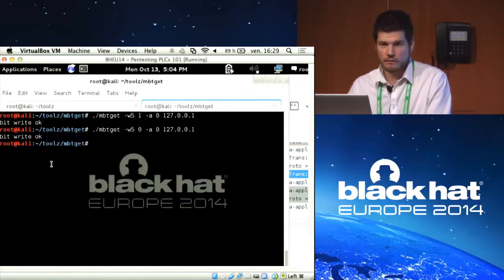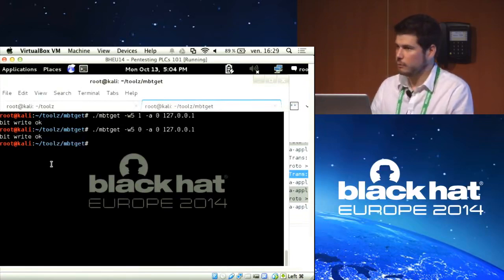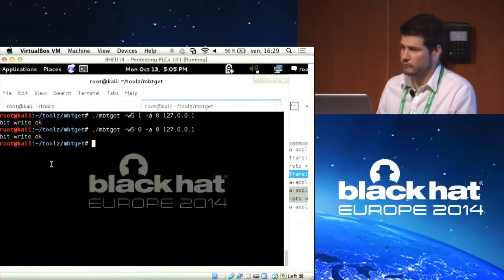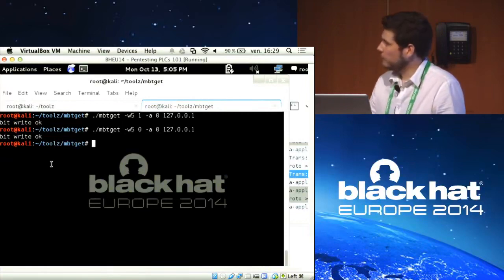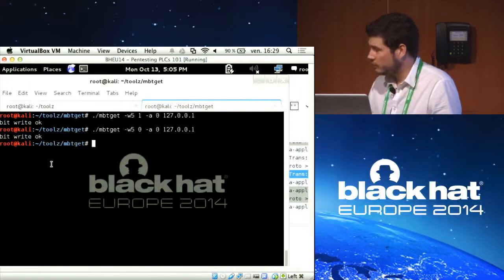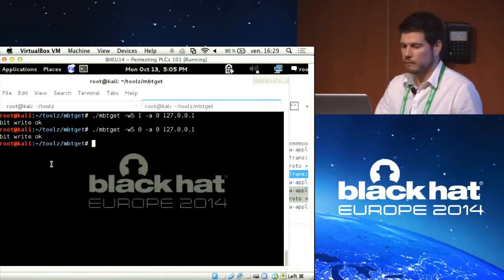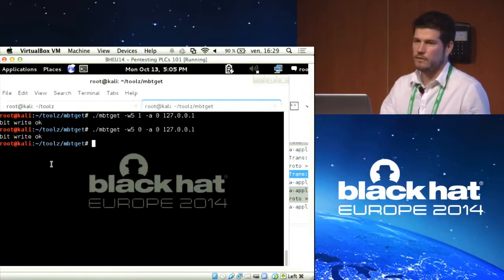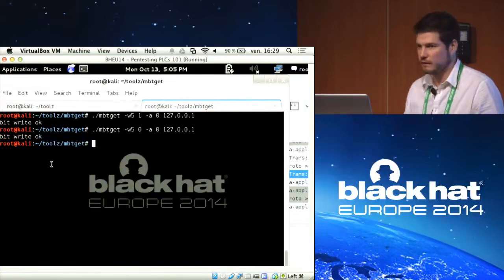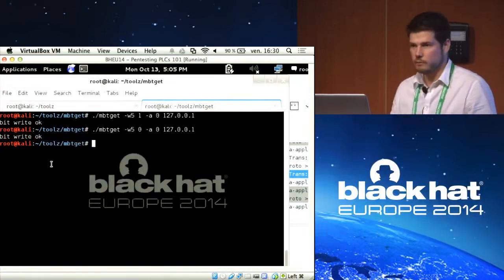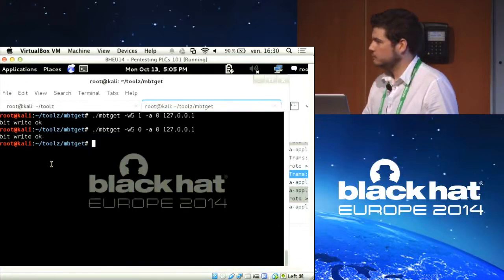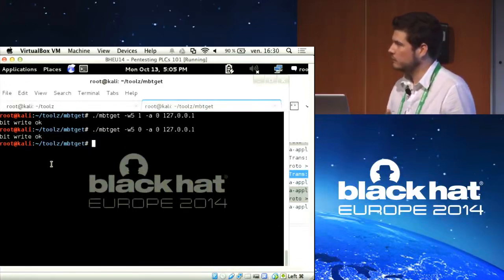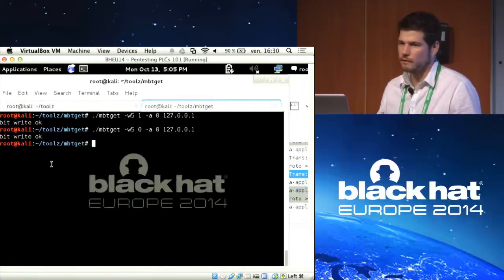Okay, great. I think if you do not have any other question, we can take our break. What are we going to do after the break? We're going to do the same kind of request using Metasploit, because there is an integrated Modbus client auxiliary module. And then after, I'm going to try to set up a Wi-Fi network, so those of you who are interested can perform the same test as me on the real devices. And by those tests, I mean performing some kind of recon using Nmap or PLC scan. Then we are going to use the same tool, mbtget or Metasploit, to perform a Modbus request to the Schneider PLC. And then I'm going to try to show you, let's say, 1 or 2 vulnerabilities in the Schneider PLC that allow an authenticated stop and start, or maybe we can try to retrieve the program without being authenticated.